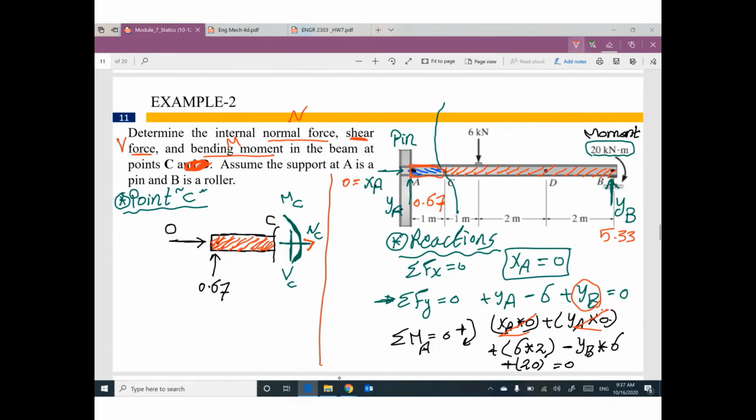What about shear? Your shear must make this part of the beam rotate clockwise. If this force is coming down, this part can be rotated clockwise, like this. For the moment, we need to make this part of the beam smile. Here is the direction of the internal forces.